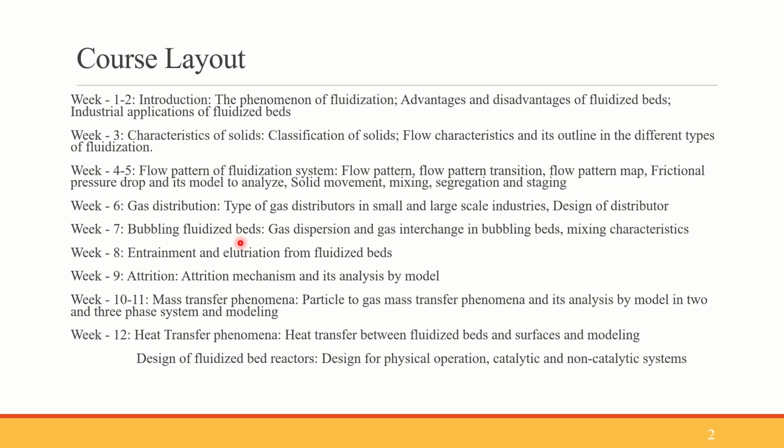So what is fluidization? Fluidization is the process in which we pass a fluid at a sufficiently high velocity so that the particles start behaving like a fluid, and therefore we gave the name fluidized beds. The advantages are that it can offer enhanced heat and mass transfer rates because of the increased surface area. Similarly, we have disadvantages like attrition and loss of materials from the bed, as we have seen in the last weeks and will also see in today's class.